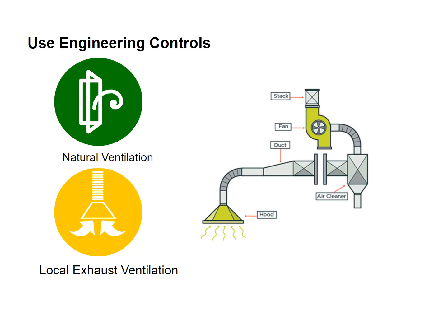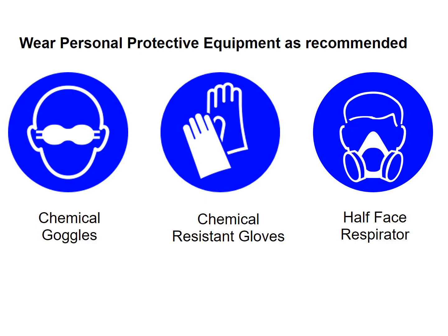As a best practice, general ventilation is recommended to reduce any droplets in air when working with these products. If the application involves spraying, use local exhaust ventilation or other engineering controls to maintain airborne levels below recommended exposure limits. When working with aspiration hazards, wearing personal protective equipment, PPE, including the recommended respirator, is essential in preventing exposure. It is critical to follow the controls that have been recommended for the job.